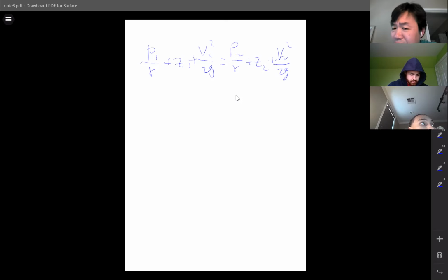Do you think so? Velocity is relatively easy because if the velocity is constant and you have a cup with a known volume, you can measure the time to fill this cup. Volume per time is the flow rate, then divided by cross-sectional area, it is the velocity. So it's measurable. Elevation is easy to measure. Pressure, like I said, is difficult to measure. If you have a pressure gauge, go ahead and use it. Sure, that's easy to measure if you have a pressure gauge. If not, maybe just avoid measuring pressure.